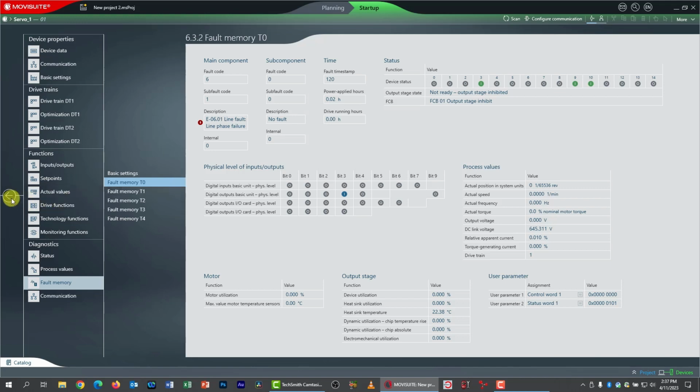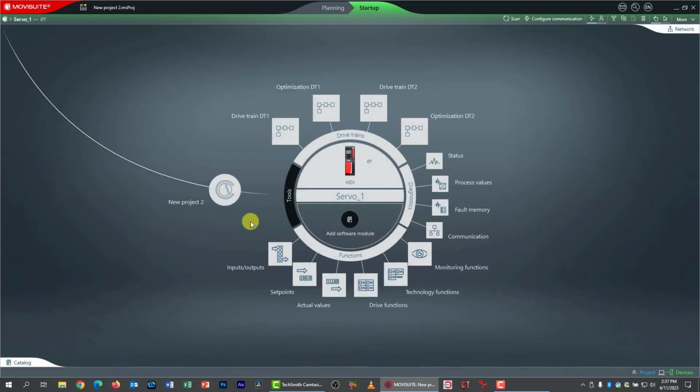All right, we're going back to the access circle. Just one more thing to do. We want to name our VFD to something appropriate to this class. I am using an asynchronous motor, and that is my assumption as to what you're using. So I'm going to change the name from servo to async1, which is a little more appropriate. Of course, if you don't have an asynchronous motor and you're going to use a servo motor, you could name yours servo1 if you want. I'm just following the instructions, and that's the kind of motor we usually use when we teach this class live.